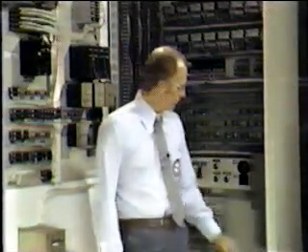So far, we have identified the three subsystems that control the servo actuator. The next electrical control subsystem controls the output of the generator. The voltage regulator, VR260, controls the output of the generator. The voltage regulator subsystem receives an input from current and potential transformers which monitor generator output.